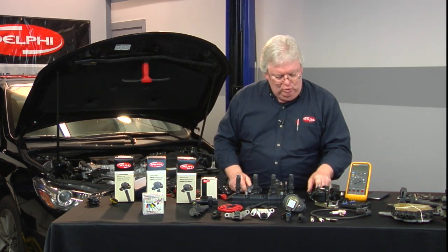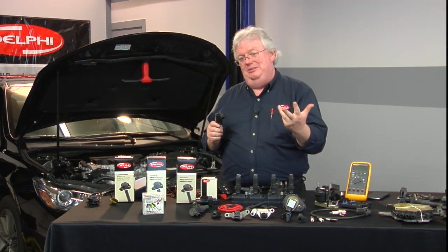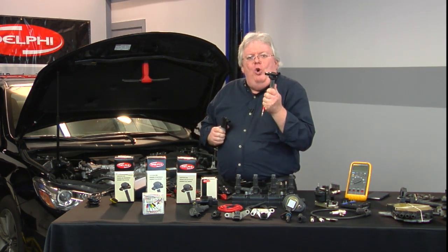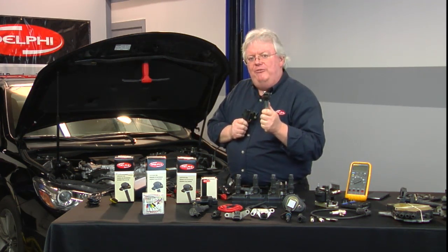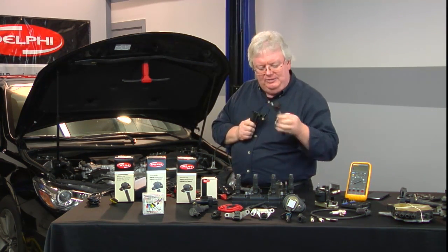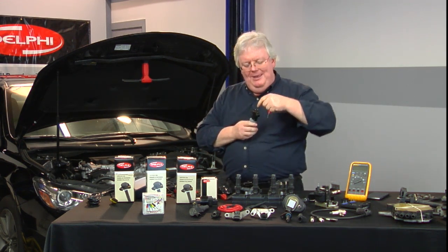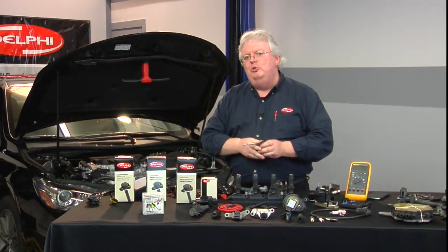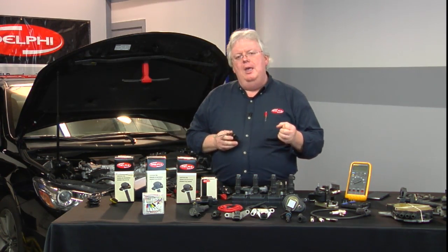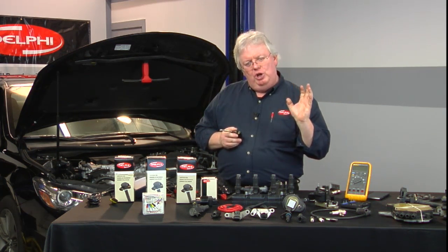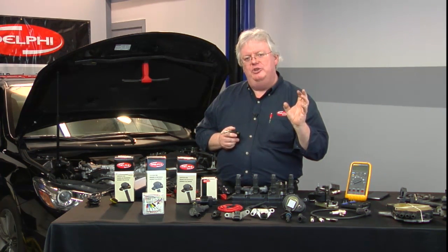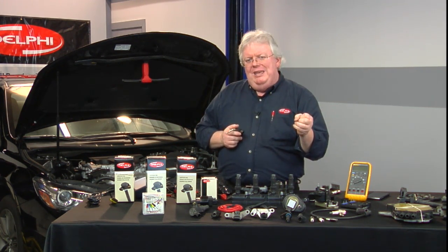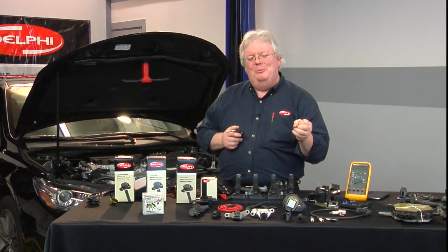Although if you had a simple 2-wire Ford, what I might be tempted to do, and I've seen this in the Toyota manual for spark plugs, you would never do this test with a Coil-On-Plug Toyota 3 or 4-wire, GM 3 or 4-wire because of the electronics. But if you just got a plain old simple primary and a secondary winding, and some terminals and so forth, you could take a Fluke 1587 or similar megohm meter that puts out low current but up to 1,000 volts of energy. It's usually used for checking those orange cables on hybrids to see if they got a leak somewhere. You won't get shocked if you touch this 1,000 volts. You'll get tingled, but it won't hurt you.